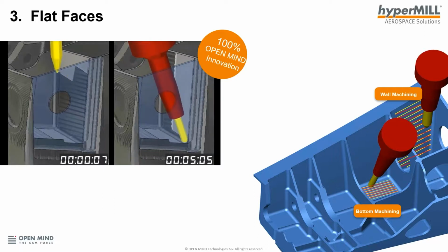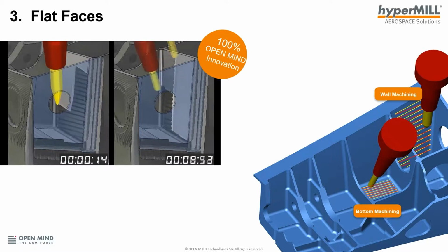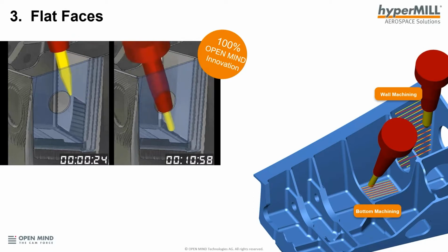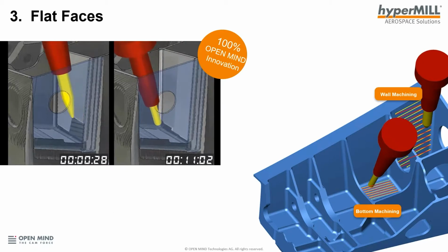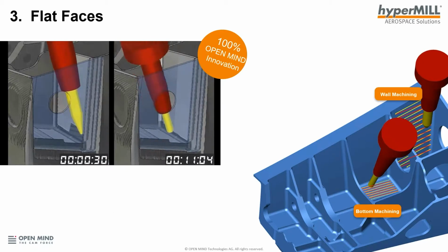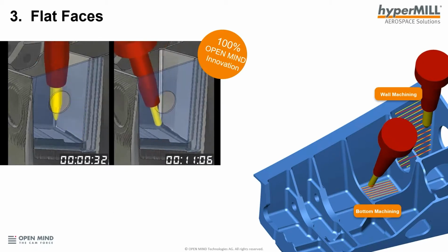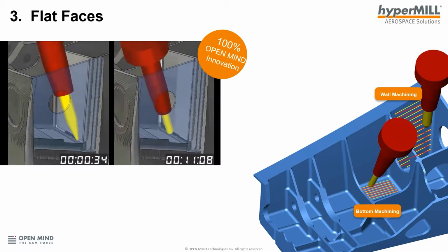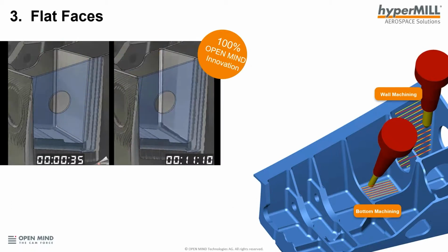So you can see here what it's doing now in the far left-hand picture is that it's actually indexed, so it's a 3+2 operation. This is a really nice toolpath for gantry style machines that aren't so dynamic. It's a really nice result for these types of machines, and the two toolpaths have a special blending macro between them, so you can't see or feel the witness arc between these two toolpaths.